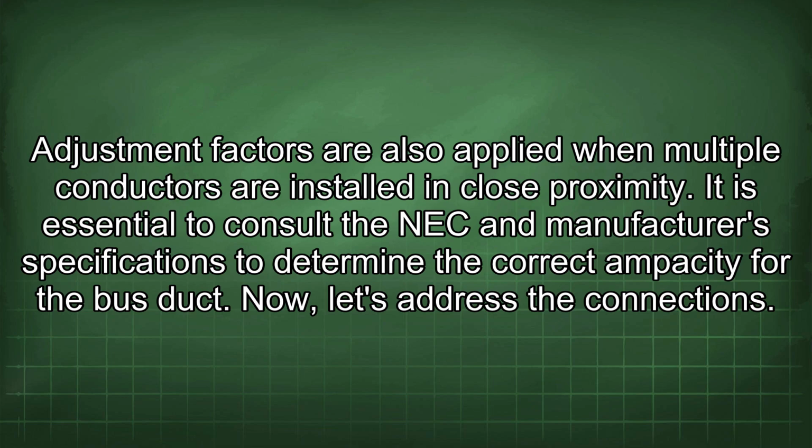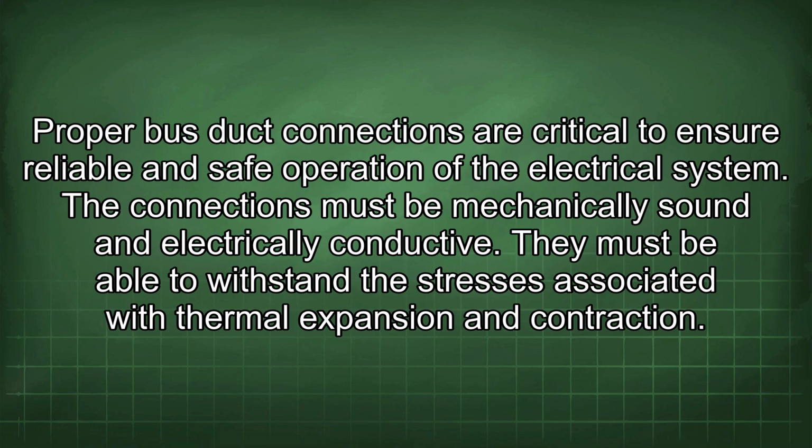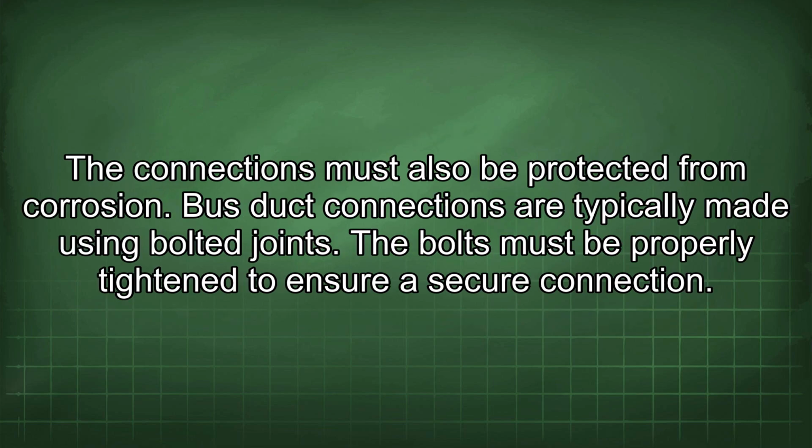Now let's address the connections. Proper bus duct connections are critical to ensure reliable and safe operation of the electrical system. The connections must be mechanically sound and electrically conductive. They must be able to withstand the stresses associated with thermal expansion and contraction. The connections must also be protected from corrosion.